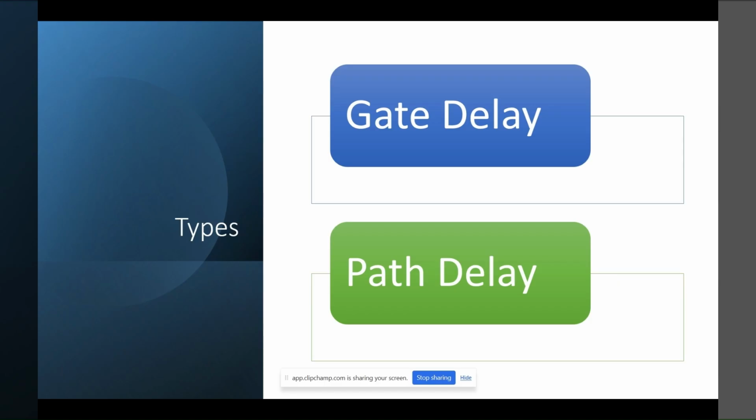As mentioned in the previous videos, the manufacturing defects in VLSI can be represented using various types of fault models. The size of the defect determines whether the defect will affect a particular output of the circuit that is designed or not. Smaller defects, which are likely to cause a partial open or short in a circuit, have a higher probability of occurrence due to the statistical variations in the manufacturing process. So these defects result in the failure of a circuit to meet the timing specification.